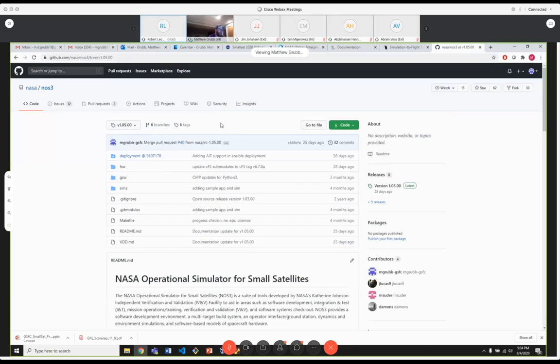As far as I know, the thruster is configurable for whichever thruster you are modeling after. You give it your maximum thrust, and you would model whether it's a cold gas thruster with a specific impulse or an ion thruster that's going to speed you up over time. It would be up to the 42 model that you create for your thruster.